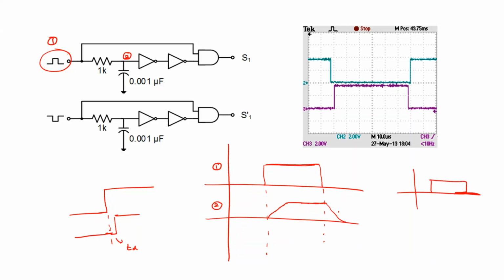So when you apply only this RC circuit, the resultant waveform is shifted by some time period delay. Instead, we need to remove the delay, or stop it exactly at the falling edge.